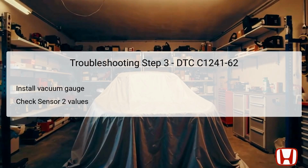For the third troubleshooting step, repeat the process used for sensor 1, focusing on brake booster pressure sensor 2. This requires the same initial setup of the vacuum/pressure gauge and hose to be installed between the brake booster and the associated vacuum hose. After setting this up, confirm the HDS readings for the vacuum pressure sensor signal 2.